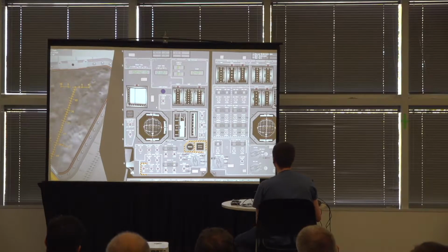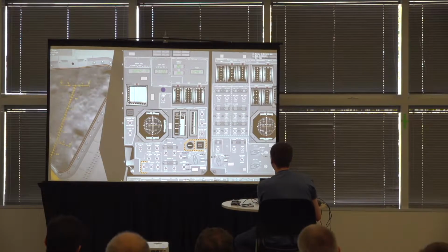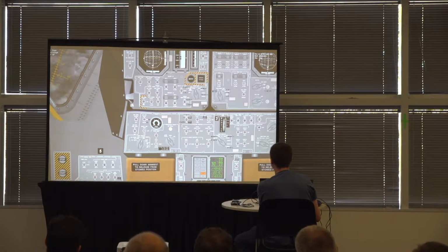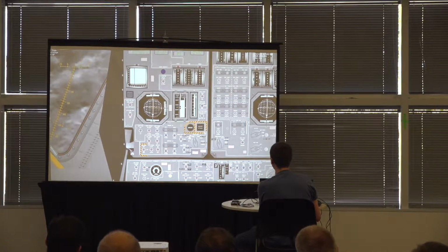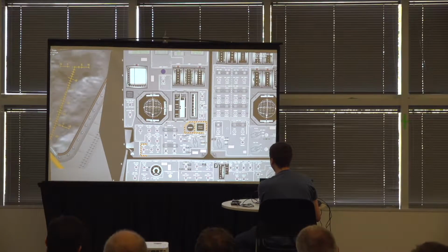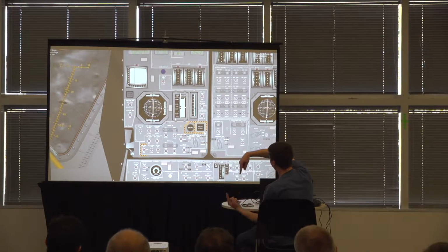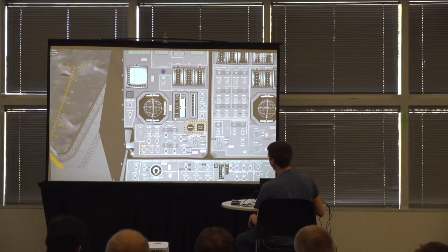So the altitude rate and altitude information being displayed in the last two lines of the DSKY here are also being displayed on the tape meters. The AGC is sending this information out to this display too. These tape meters are just tapes with numbers printed on them, and they move up and down according to our current altitude on the left and altitude rate on the right.